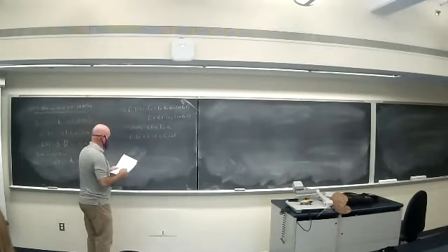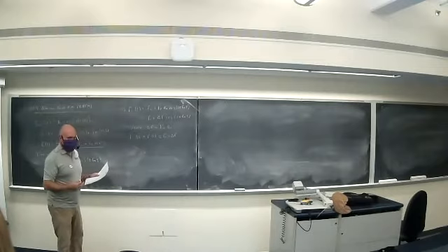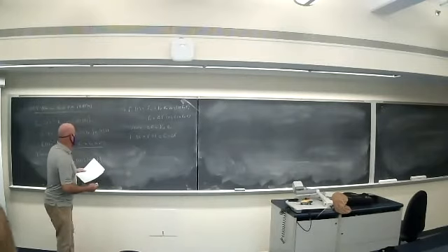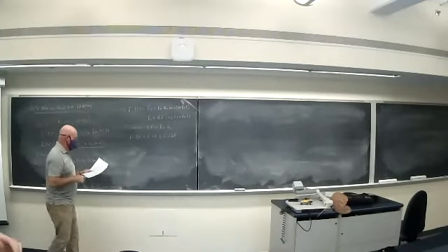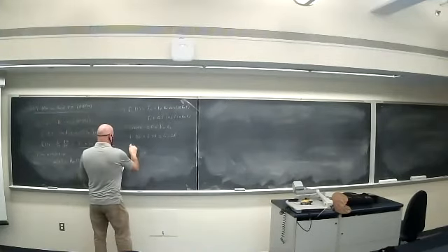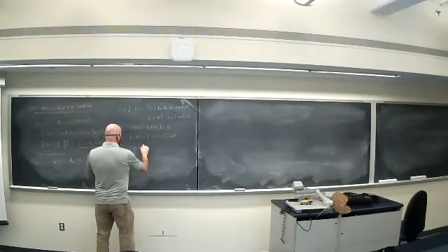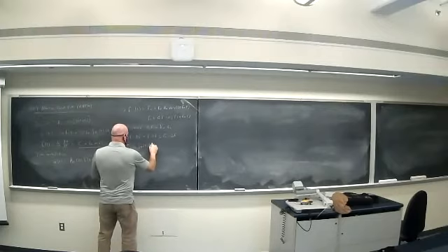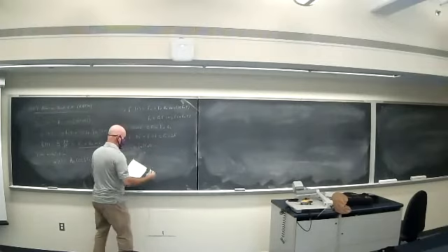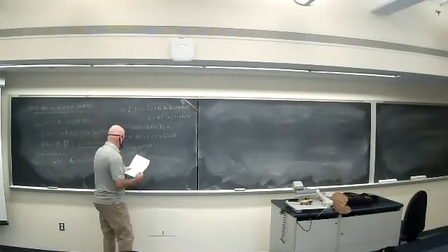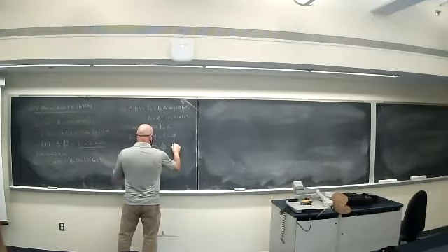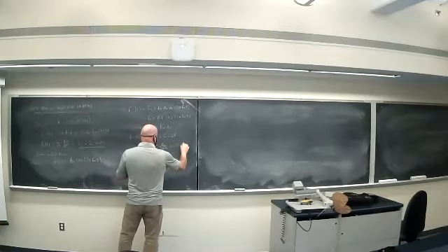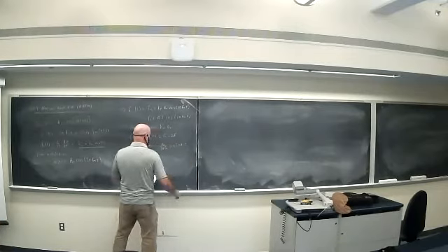Now, let's take this a little further and look at the instantaneous phase, because that's what we need to look at to start talking about the Fourier transform of this thing. Because this is just a tone, we can integrate it. I started with a cosine, so I'm going to get 2 pi FM sine of 2 pi FM t.